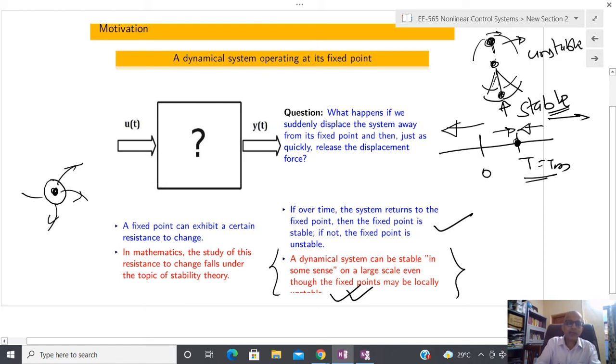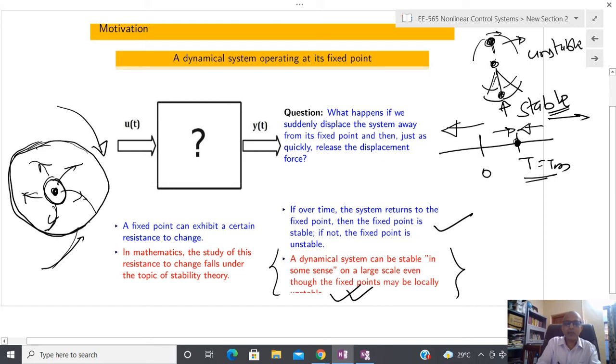And it is possible to show, in the case of a limit cycle, that I have some connected equilibrium point here. If you start from far away, you are going to converge, but if you start nearby, you are going to diverge, and finally you are going to converge to this particular orbit, and this is called a limit cycle.